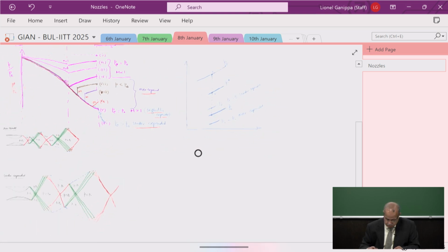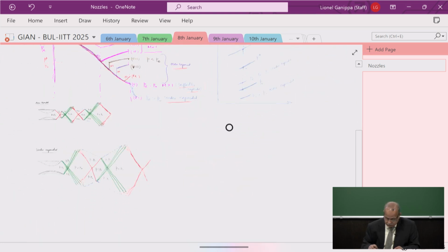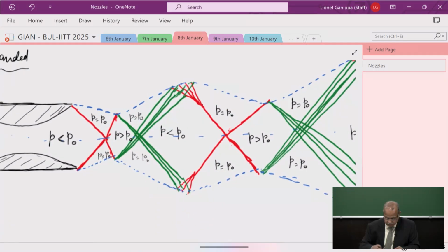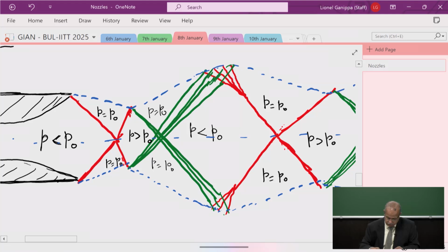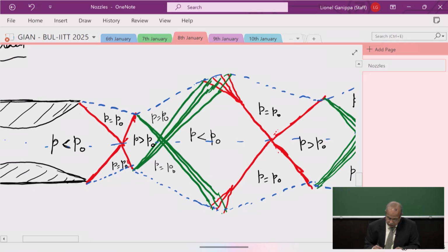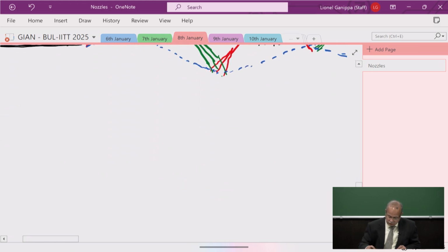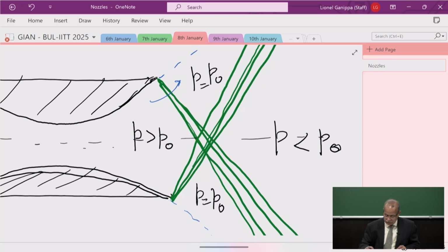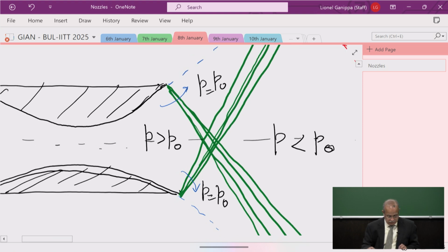Okay, so we have done enough problems with the shock waves. So when we have flow encountering an oblique shock, the flow turns into it. Now, when we have a flow encountering an expansion fan, the flow turns in this direction here.